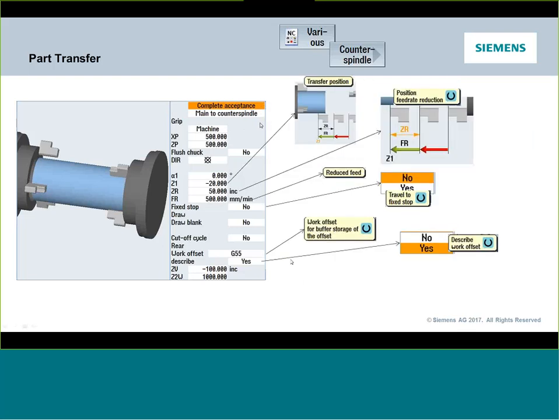Okay. Now from there, we then got to look at where the physical sub spindle is going. This is really where the rubber hits the road. So Z1 is an absolute position relative to your G54 or whatever work coordinate is set to the main spindle. The system, because it knows all the chuck data and projections, will automatically bring the sub spindle over and grab the part.